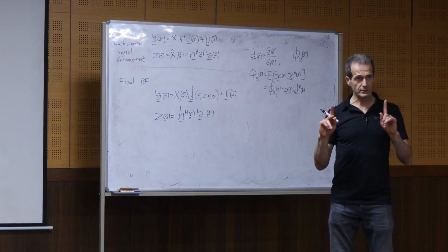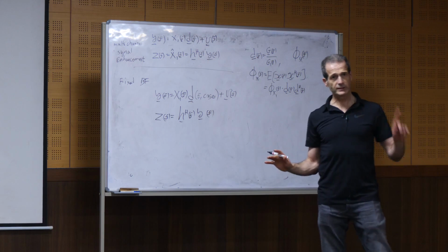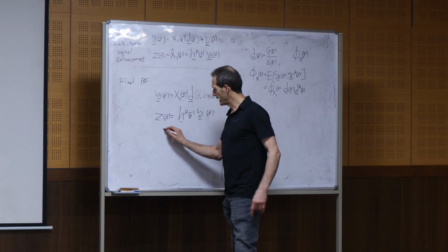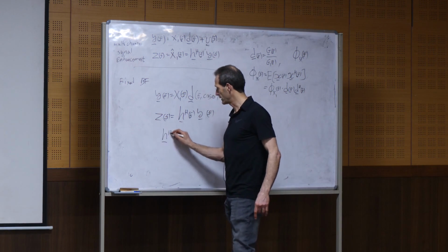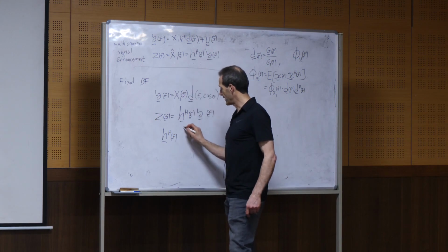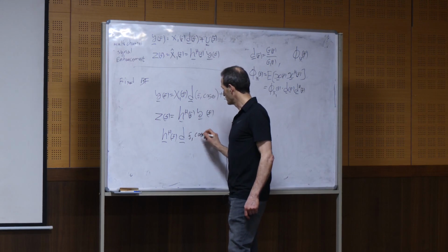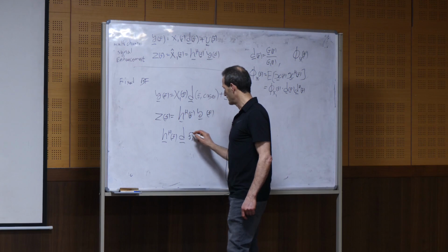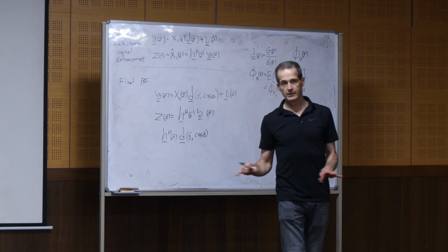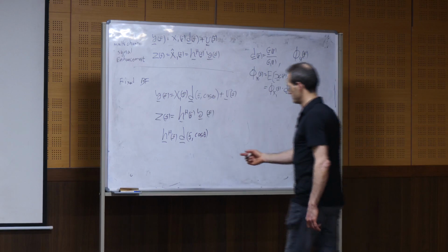I know the direction, and I don't know the reflections, so I don't take the reflections into account. So what I require is that if I apply the filter that I find to a signal that comes from that direction, the steering vector, the far-field steering vector without any reflections in the environment, I know that.